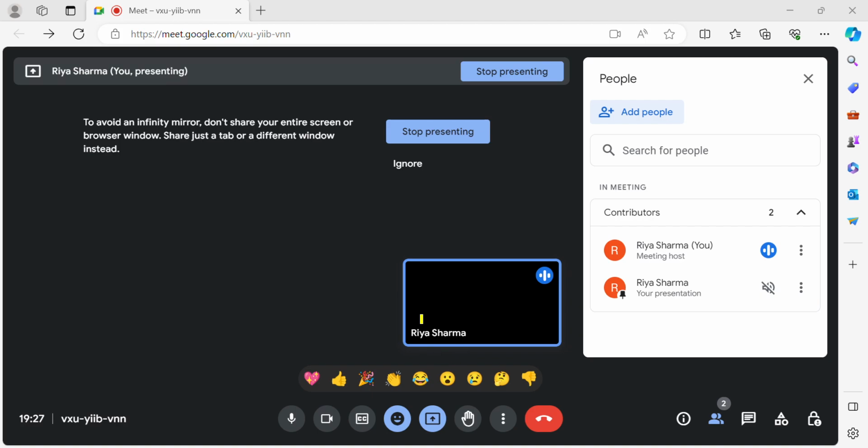So whatever your kilogram per hour value is, convert into kilogram per second. How will you convert? 1 hour is equal to 60 minutes, and 1 minute is equal to 60 seconds. So 1350 divided by 60 into 60, the value will come around 0.5192.